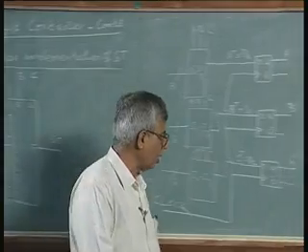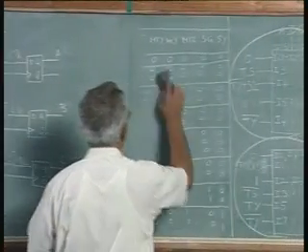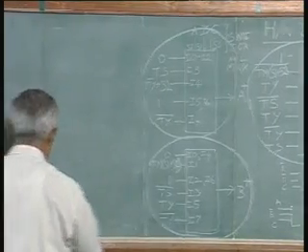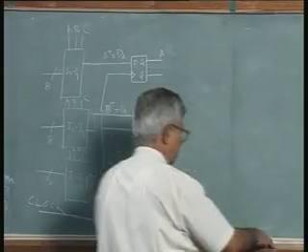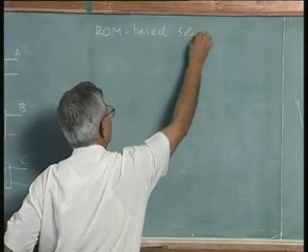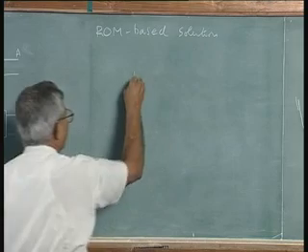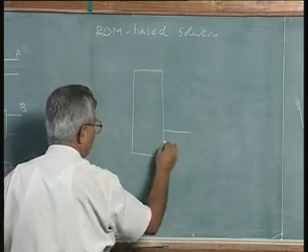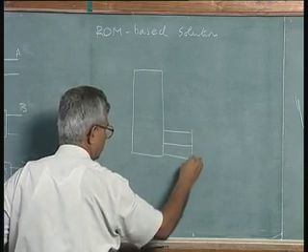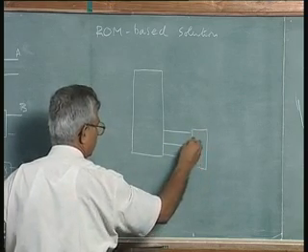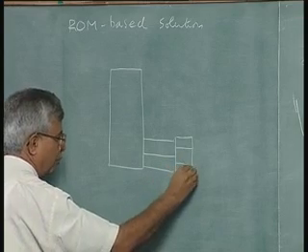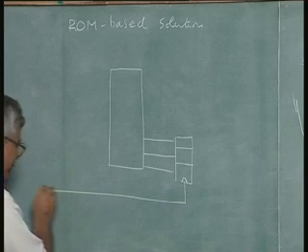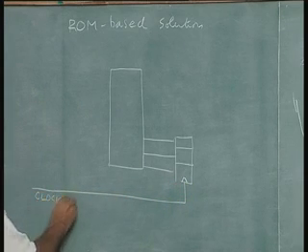Of course, you want to have a ROM based solution for this. Yes, it is possible. What will be the size of the ROM that will be required? We have 8 states. Supposing you have a ROM based solution. What do you mean by ROM based solution? The ROM keeps everything and drives the flip flops. Let us call these flip flops a register, 3-bit, with a clock which is common to all the 3.